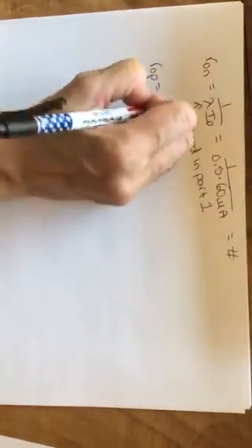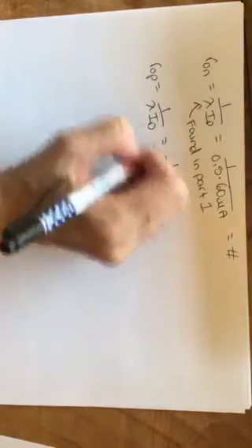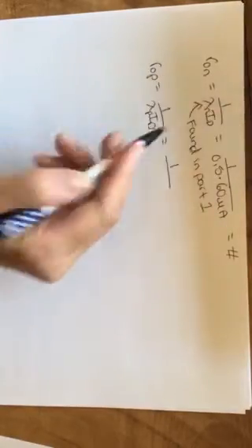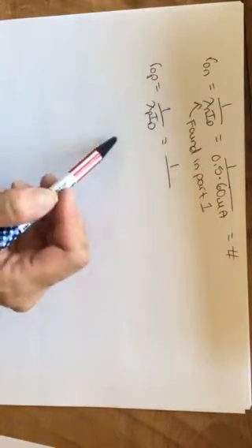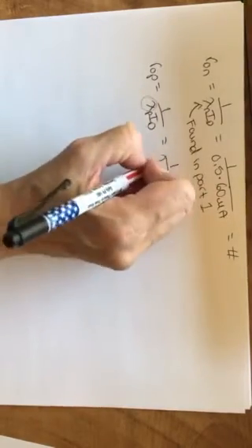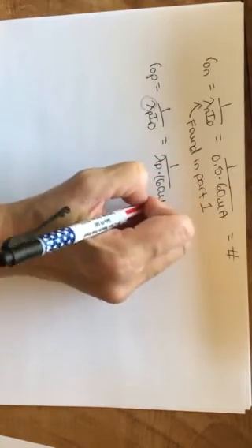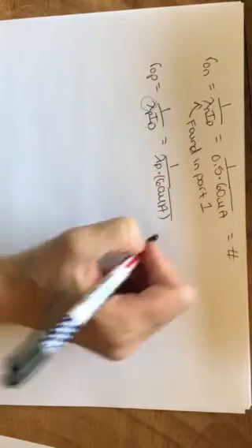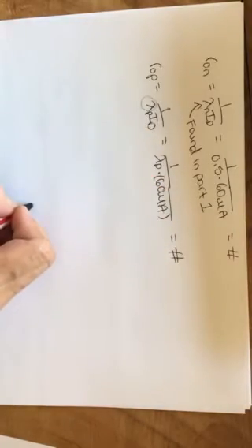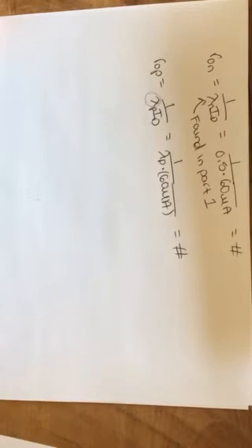r naught P is 1 over lambda ID, same ID. Again, you find the lambda of the PMOS and NMOS. I'll call them lambda N and lambda P because they're not equal. You will find this through part 1, and you have your current, 60 microamps. I'm going to leave it as lambda P, and you'll find some number. I was making the assumption lambdas were 0.5, but for this analysis, I don't need actual numbers here. I just want to show you what happens to the gain of this system.